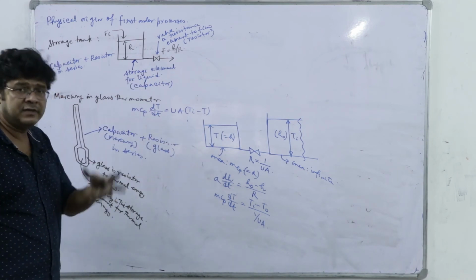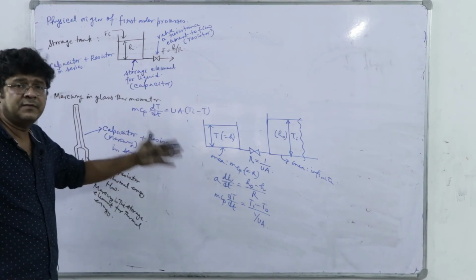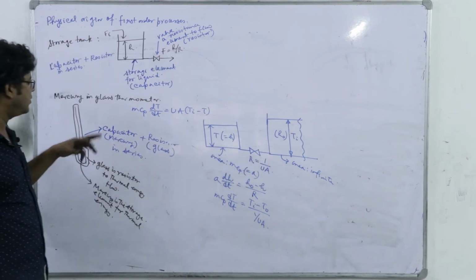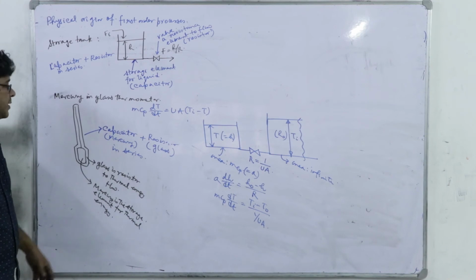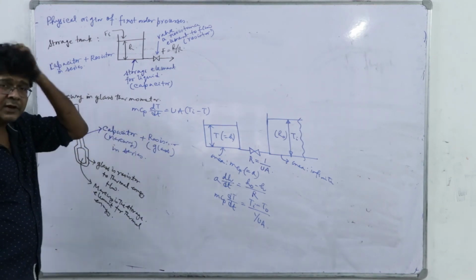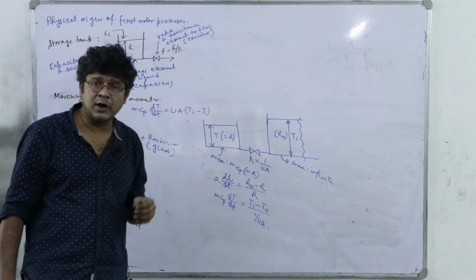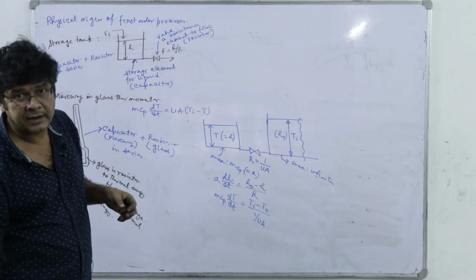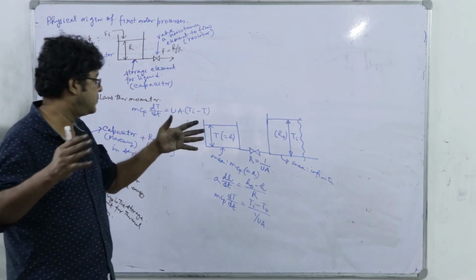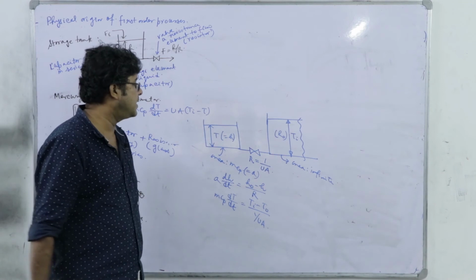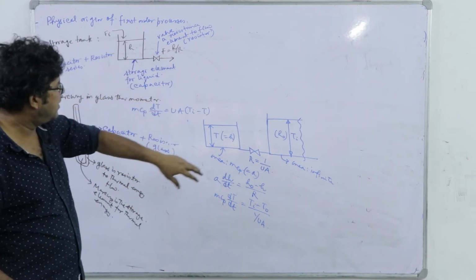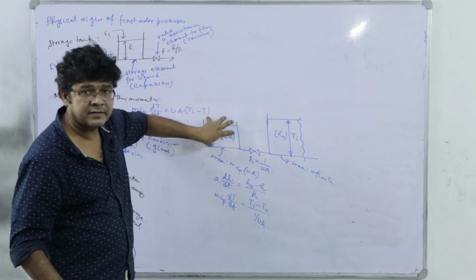Mercury in glass we can map in terms of a storage tank, which is receiving its delivery from an infinite cross section storage tank. Why infinite cross section? Because the surrounding is of infinite heat capacity and mass. If you abstract or give some heat to the surrounding, its temperature is evidently not going to change. So, that is why in the tank analogy it must be considered as a tank with infinite cross sectional area. So, this is again a resistor and capacitor system.